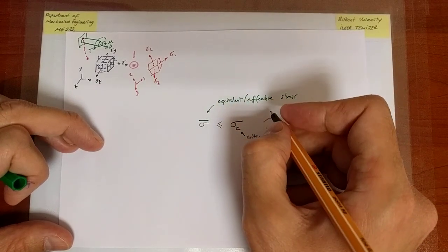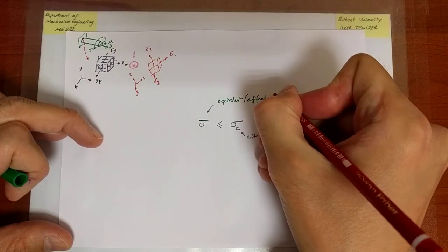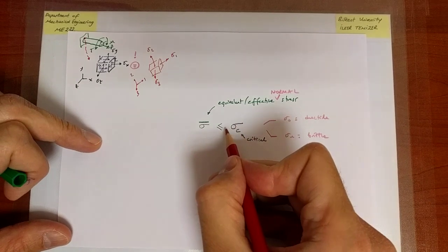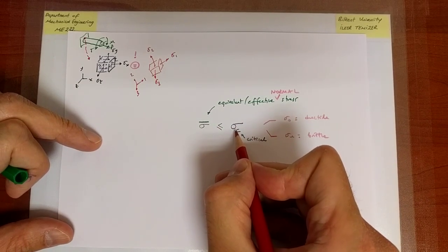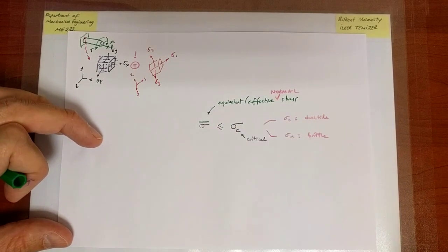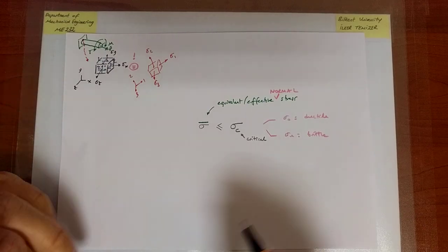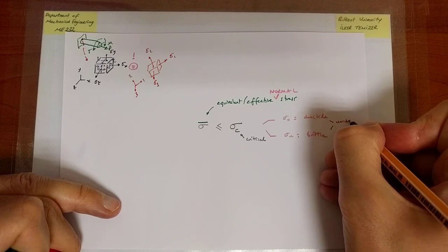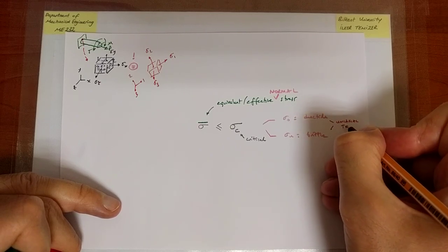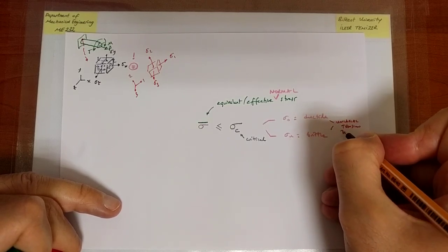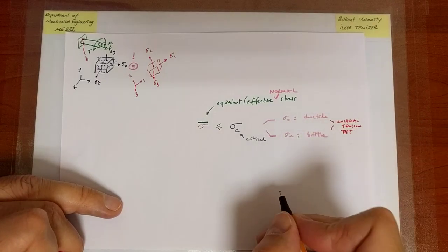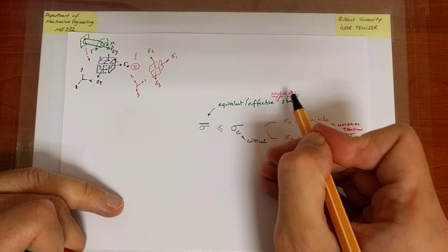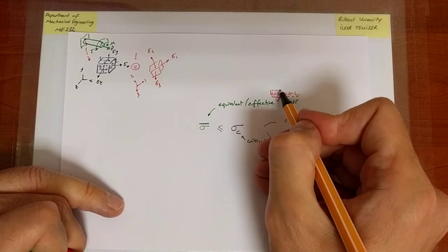And it is, notice, importantly, a normal stress, because the comparison value is a value that comes from a uniaxial tension test, which delivers a limit to the normal stress which I can apply on the material.